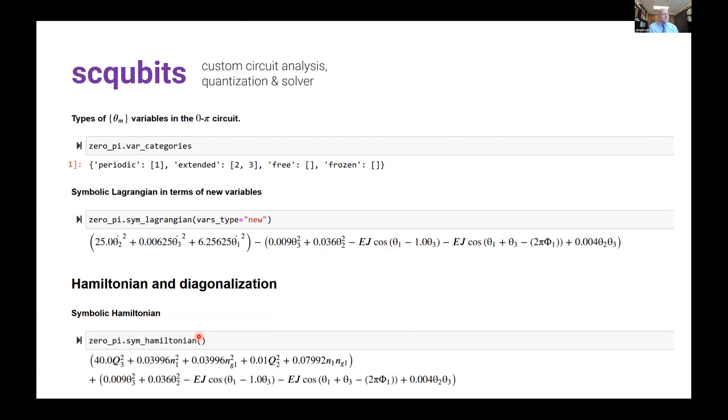And I can guarantee you that there's a particular parameter regime. So I've specified the circuit, it has a certain size, but now if I play with the parameters that characterize that circuit, I can easily enter parameter regimes where it becomes quite hard to do numerical diagonalization. And in fact, so hard that you will have trouble getting it to converge with this package. On the other hand, I know of circuits where hundreds of nodes is just fine. Hundreds of nodes, maybe even thousands. If you have a circuit that only consists of L's and C's, so it's just coupled harmonic oscillators, that is a special case that we recognize as well and treat differently, and it's very easy to handle.